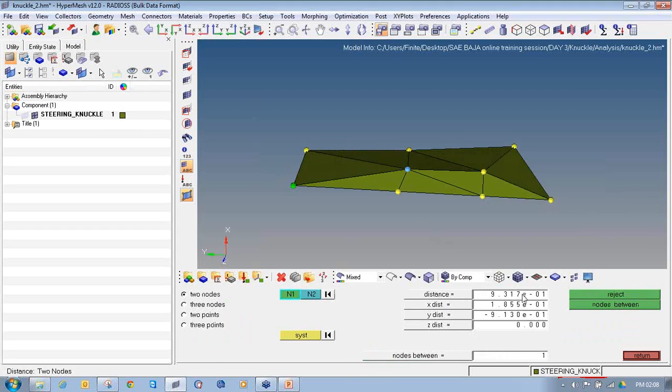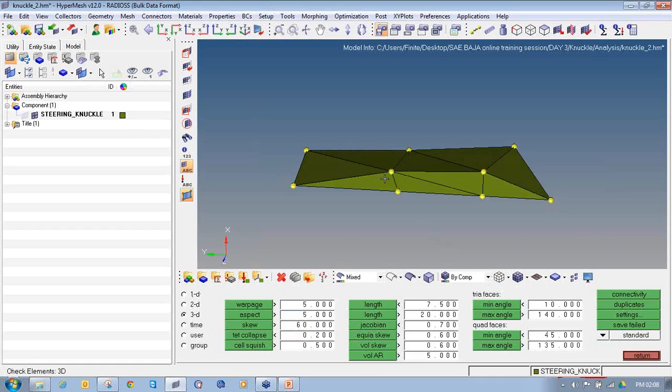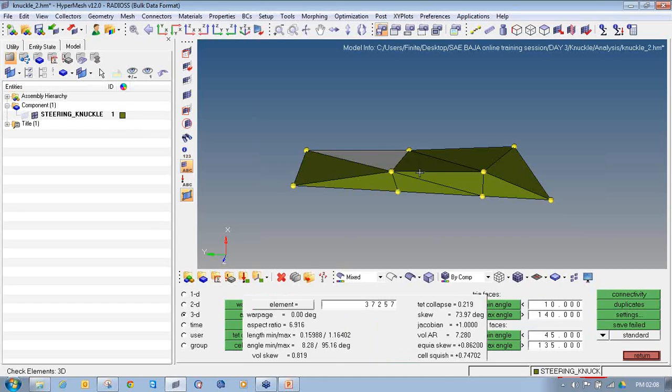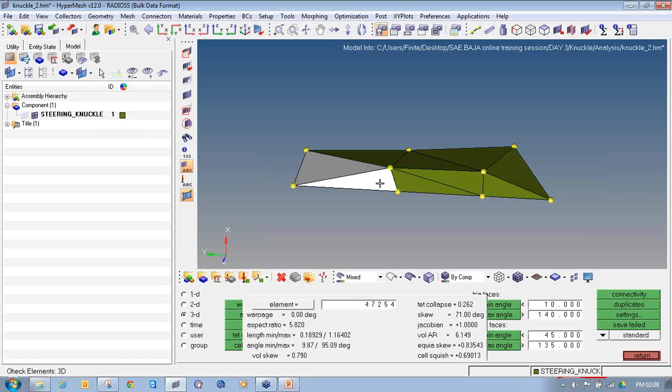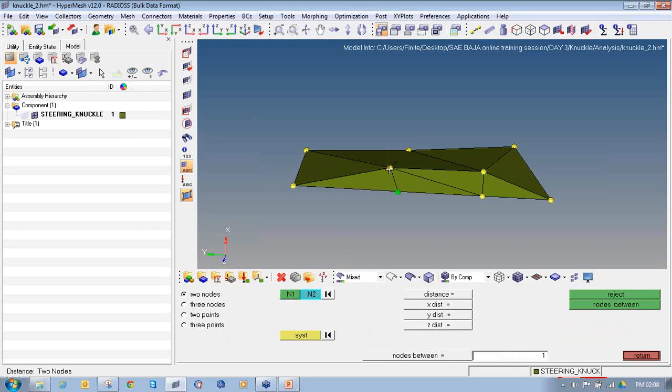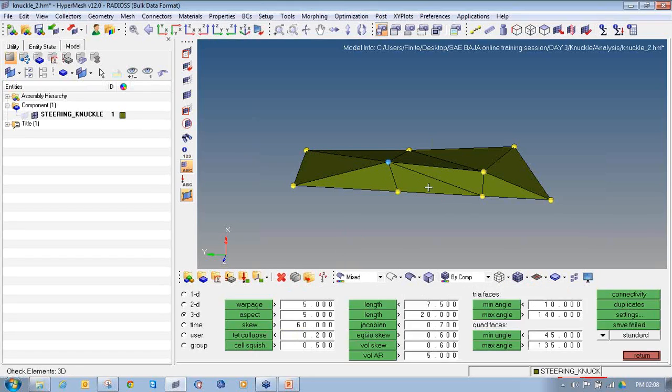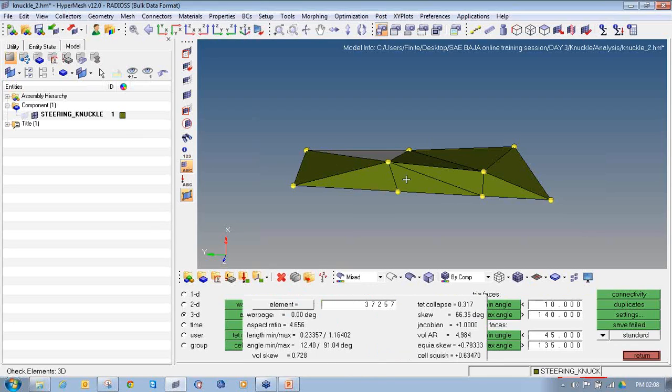This will also help us to clear the Jacobian, aspect ratio. So it's coming as 6. So again I will improve the little bit height to say 0.2. Go to F10 again, 5.8, 5.8. I'll increase a little bit more height. So 0.25. Again F10, 4.6, 4.6, 3, 5.5, 5.5 and 3.